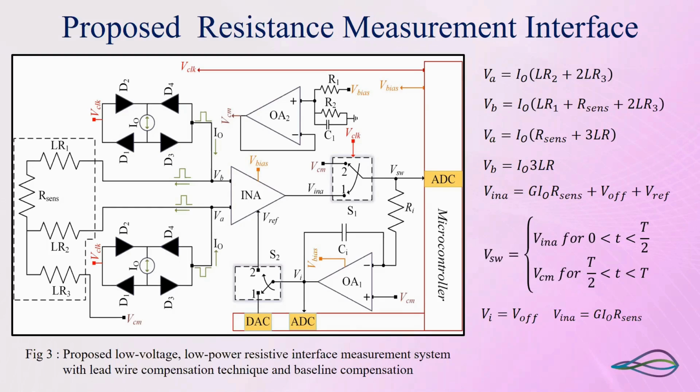Now, the voltage VSW is a quantification of our sense. However, what happens, our sense includes the baseline resistance and the incremental resistance as well. Now, at first, what do we do to calibrate the system? We take this value when no measurand is present. So the value of VSW corresponds only to the baseline of the measurement of the sensor.